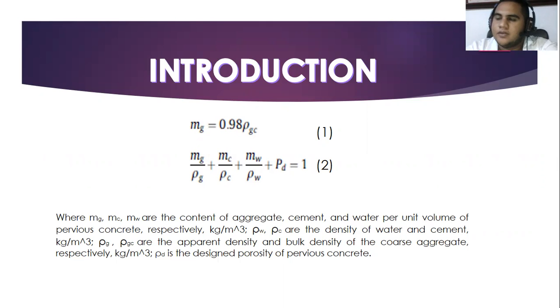It was also observed that in the compressive strength, the most influential factor is the paste content, and in the traction and bending, it is the type of aggregate. The aggregate content is determined from equation 1. Equation 2 is used to determine the cement content.